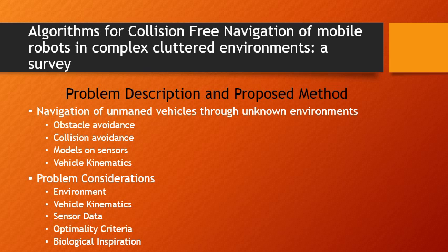Holonomic kinematic drive vehicles have control capability in any direction. Unicycles are associated with a particular angular orientation which determines the direction of the velocity vector. Bicycle kinematics describe car-like robots which are considered to have a steerable front wheel separated from a fixed rear wheel. Commonly, vehicles with bicycle kinematics will be subject to an absolute bound on their path curvature.